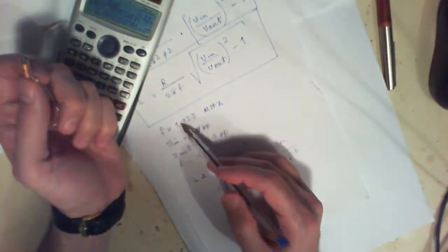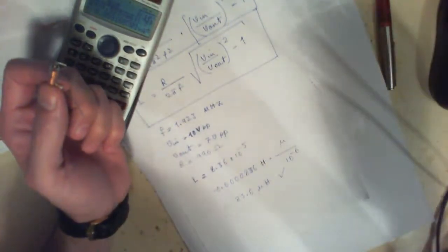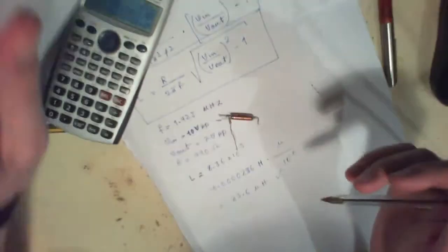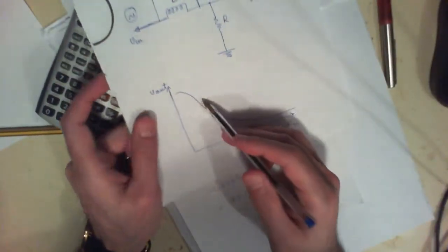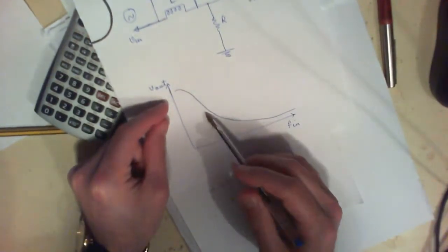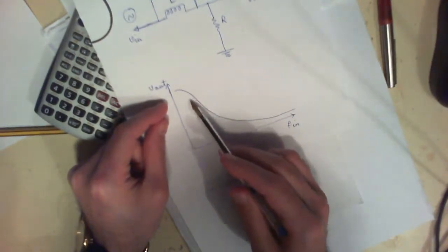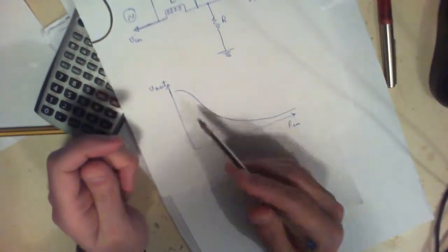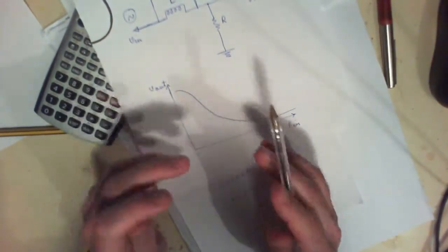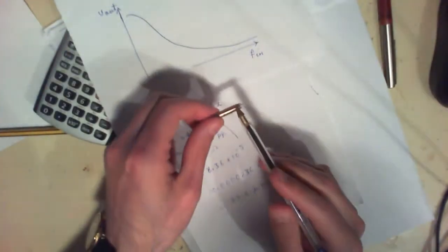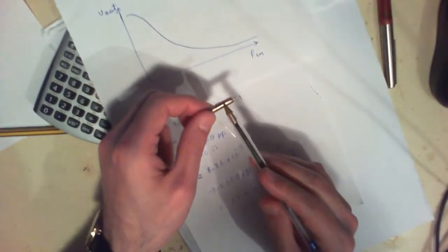So I needed only about 2 megahertz in order to drive the circuit to the area where the output voltage could drop, meaning that I had to drive the frequency high enough so that the output voltage was somewhere below the input voltage, so I could do the kind of calculation that made sense, right? Now, the value of this inductor was 100 microhenry.